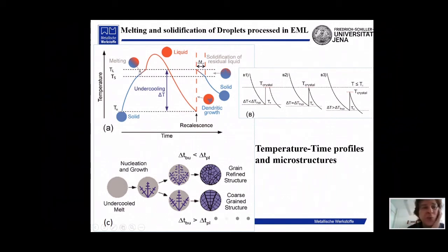when we have a liquid droplet, while before that we have a two-phase droplet. Over the liquidus temperature TL, we have a macroscopically homogeneous liquid, and if we overheat our droplet by several tens or 100 K normally, then we can theoretically destroy big clusters existing after melting in the liquid. This procedure can be repeated several times, and normally we have several cycles over the liquidus temperature, which can in principle practically destroy or deactivate all inclusions or big clusters in the liquid in order to maximally avoid heterogeneous nucleation in the liquid.